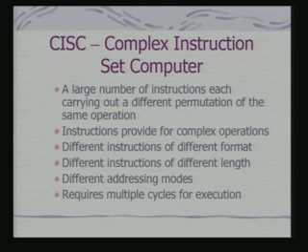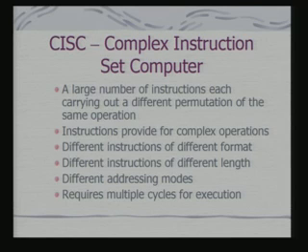What are the characteristics of CISC? A large number of instructions are typically found in the repertoire of the CISC processor, and they actually perform various complex tasks. And these instructions are typically of different length and different format, and they require in many cases different number of clock cycles to execute. Also, such processors support a number of addressing modes. So, what we find is that the basic philosophy which goes into the CISC design is more complex operations being implemented in hardware and more elaborate ways of accessing data as part of the instruction set, because that is addressing modes. Addressing modes give you a variety of ways of accessing data in the memory, and you can even have operations involving data in the memory. These are the typical characteristics of a CISC processor.